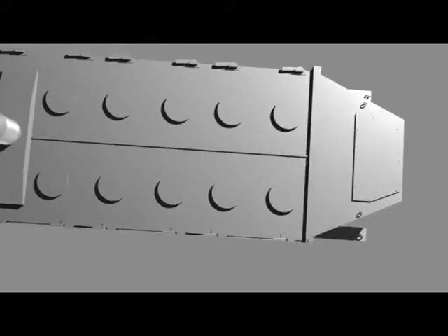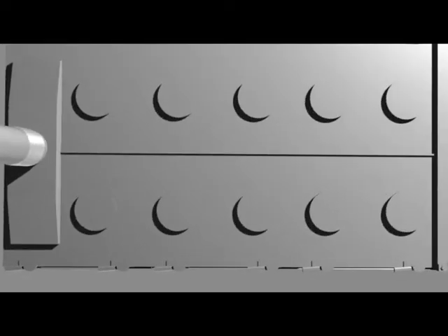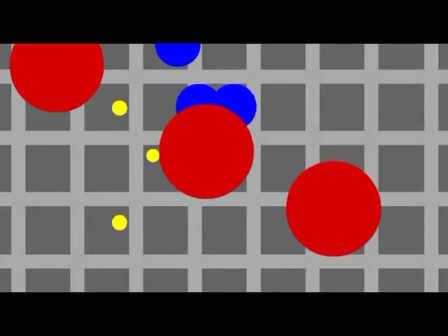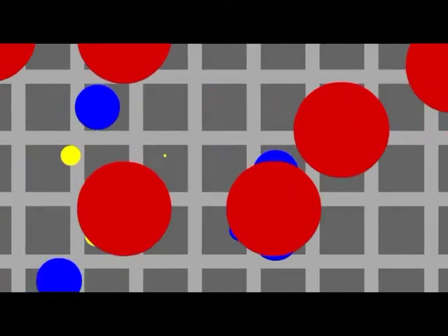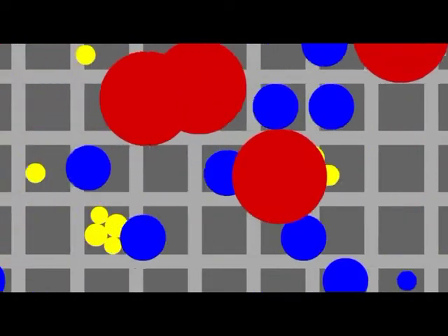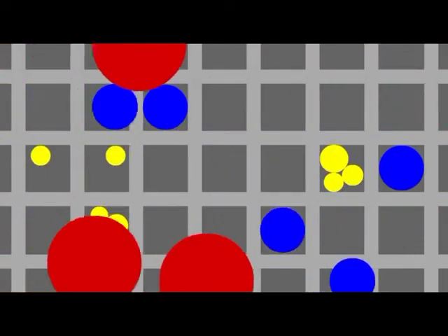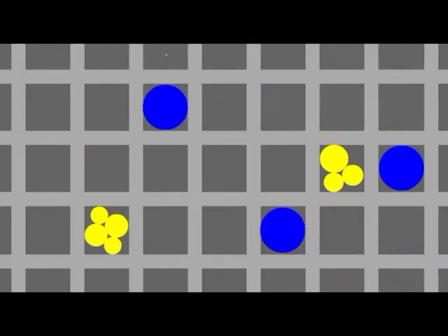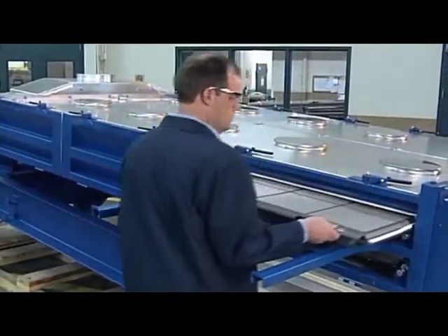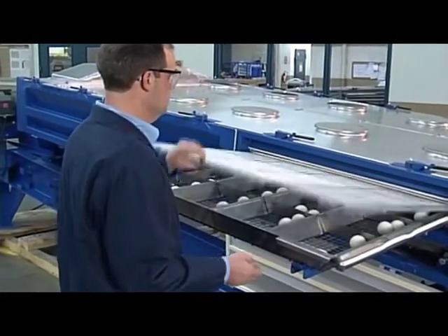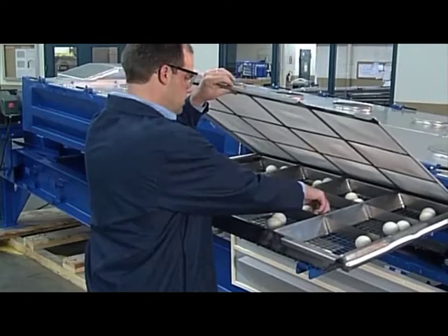All separators, regardless of their technology, are subject to clogging or blinding, the effect of which reduces the open area of the screen and therefore its performance. The more effective a separator's motion eliminates or controls the blinding, the longer it can operate without cleaning. Rotex screeners utilize a ball mesh cleaning system, as seen here, in order to control the tendency of materials to blind the screens.